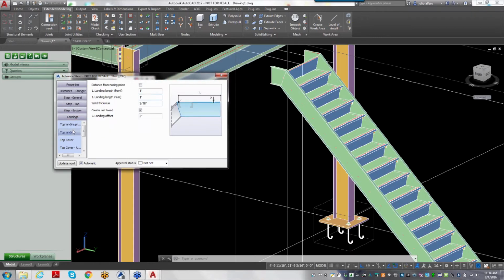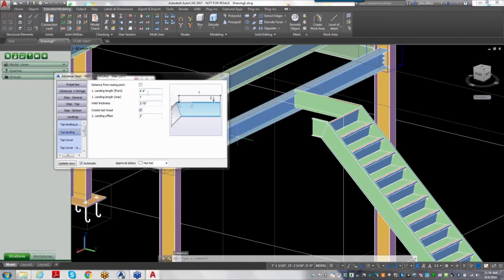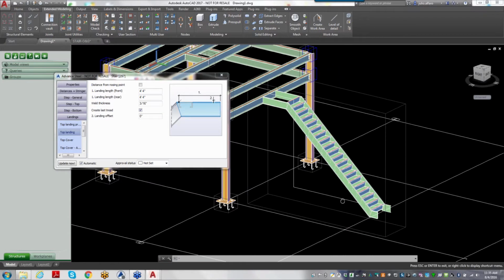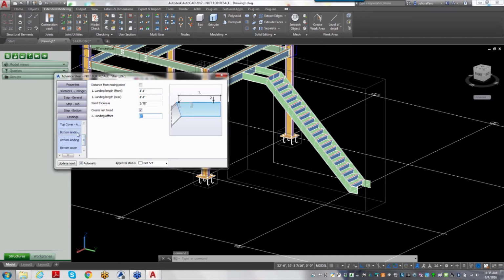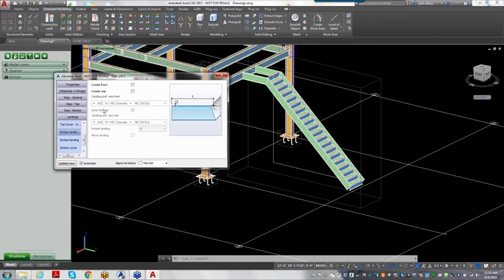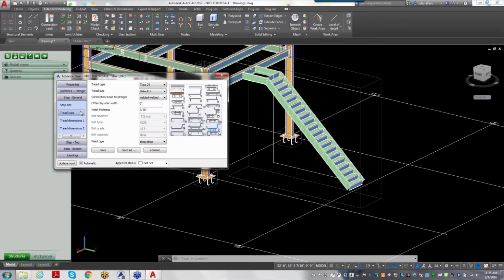All right. Just the landing, the top landing, I'm actually going to extend it 52 inches. And doing something like this in Inventor would probably take a considerable amount of time, unless it's already automated via something like iLogic beforehand. But that automation would obviously take forever. I don't think we have too many people who have rules set for stairs, for miscellaneous steel. But it's already in here. It's pretty awesome. Yeah, Advanced Steel comes with it. Everything's already set up in there, including materials and all that stuff.